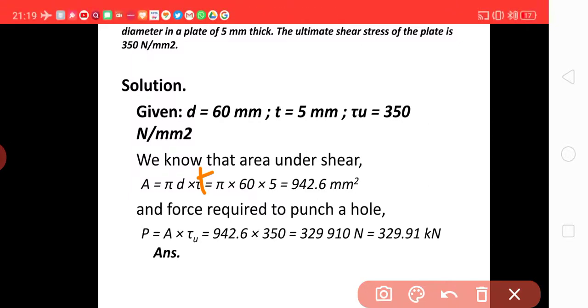So pi into 60 into 5 is 942.6 millimeter square, and the force required to punch a hole, P, is equal to A into tau ultimate, where tau u means the maximum, which is given as 350 Newton per millimeter square. So it comes out to 942.6 into 350, which is 329.91 kilonewton. This much force is required to punch a hole there.